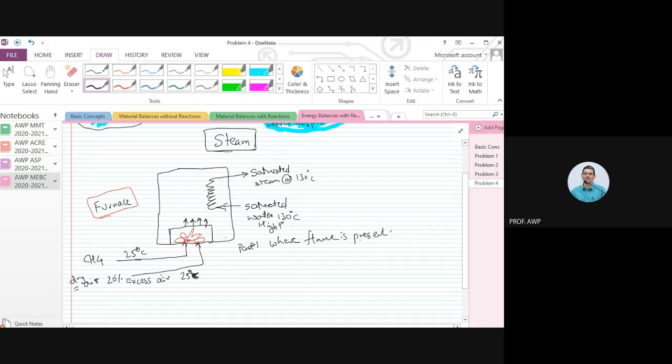Then this hot gas is my heating source that supplies the heat to this coil, which contains saturated water. It is supplied with saturated water and gets converted into saturated steam, and this hot gas will now cool, and then I can exhaust that gas. Let's say this gas that I exhaust is at 200 degrees centigrade.